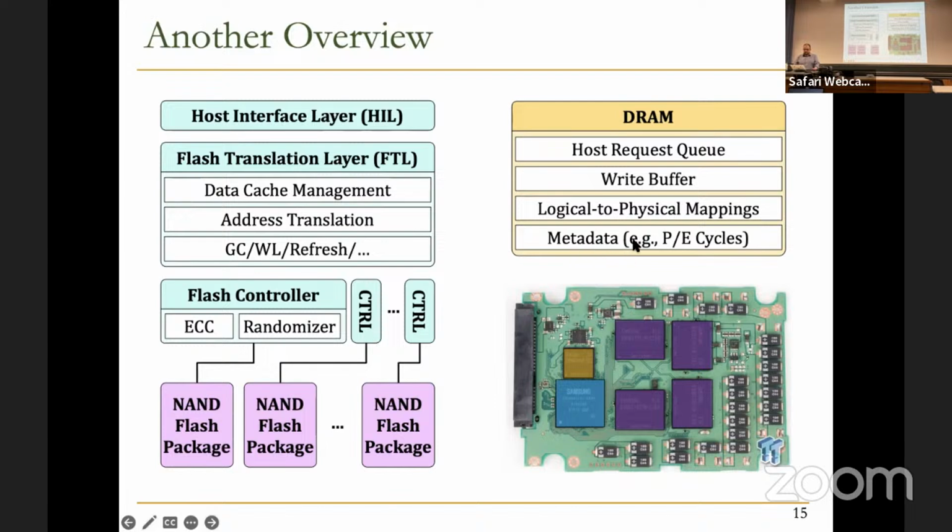There is also some metadata regarding PE cycles, program/erase cycles, that is used for other operations, such as garbage collection, wear leveling, and refreshing, essentially.